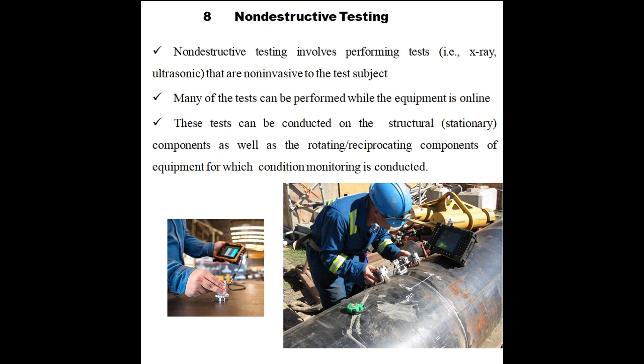Then there are certain non-destructive testing techniques also. They involve X-ray and ultrasonic testing, and these are non-invasive to the test subject. We need not touch the object. Many of these tests can be performed while the equipment is online, and they can be conducted on structural stationary components as well as rotary components.